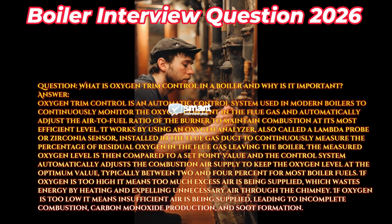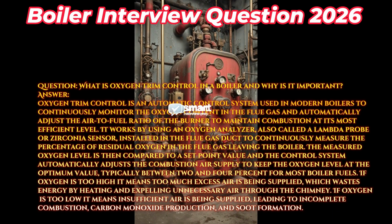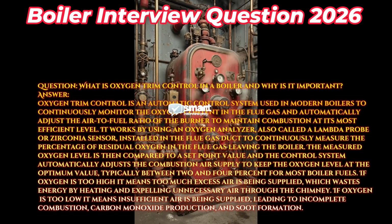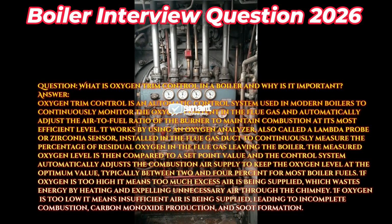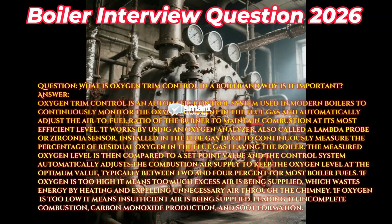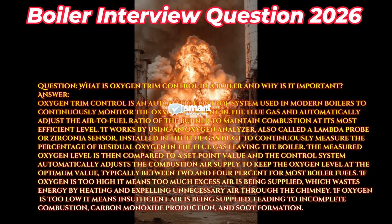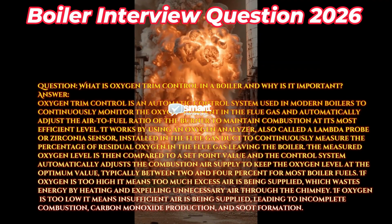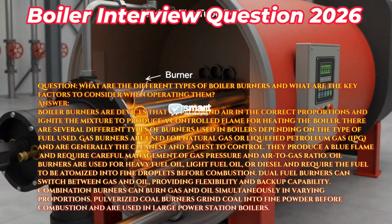boiler. The measured oxygen level is then compared to a set point value, and the control system automatically adjusts the combustion air supply to keep the oxygen level at the optimum value, typically between 2 and 4% for most boiler fuels. If oxygen is too high, it means too much excess air is being supplied, which wastes energy by heating and expelling unnecessary air through the chimney. If oxygen is too low, it means insufficient air is being supplied, leading to incomplete combustion, carbon monoxide production, and soot formation.